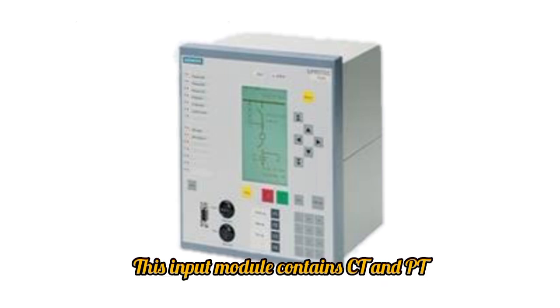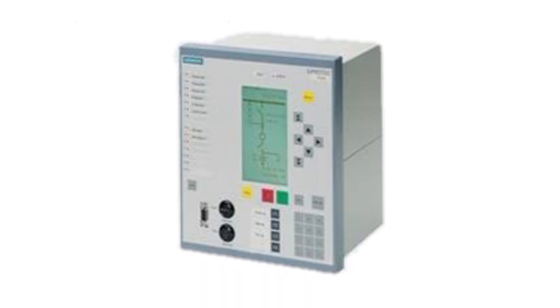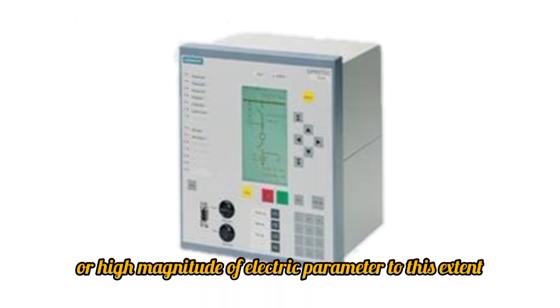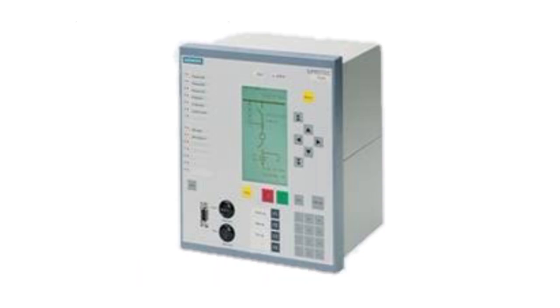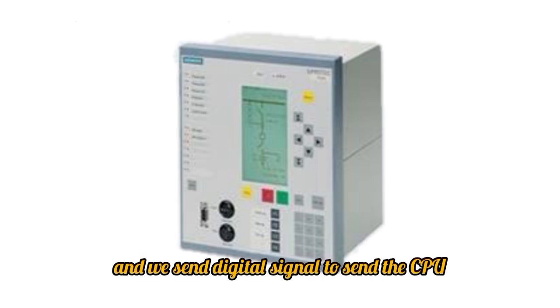This relay has an input module. This input module contains CT and PT. The function of this input module is to step down the high magnitude of the electric parameter to a level so that the relay can read it easily. The relay then converts it and sends the digital signal to the CPU.